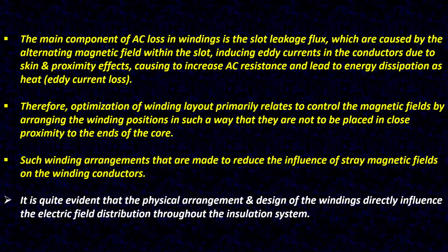Such winding arrangements are made to reduce the influence of stray magnetic fields on the winding conductors. It is quite evident that the physical arrangement and design of the windings directly influence the electric field distribution throughout the insulation system.